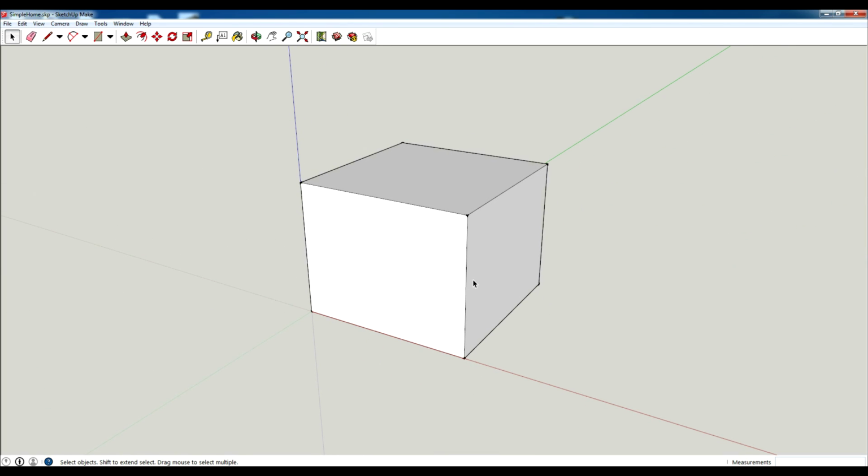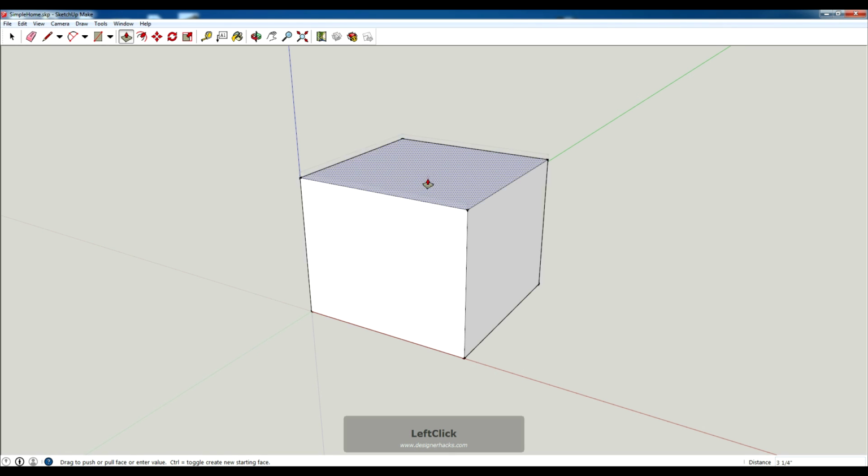Now what I want to do is make a door. So I'm going to go up. You can see right along this face, you have the edges it'll snap to, the endpoints, and then in the middle it'll snap to the midpoint on any line. So that's helpful when you want to draw something that's centered. So I'm going to go up 8 foot. So I want an 8-foot door. Oh, actually, I have an 8-foot ceiling. So I'm going to go up to 10.